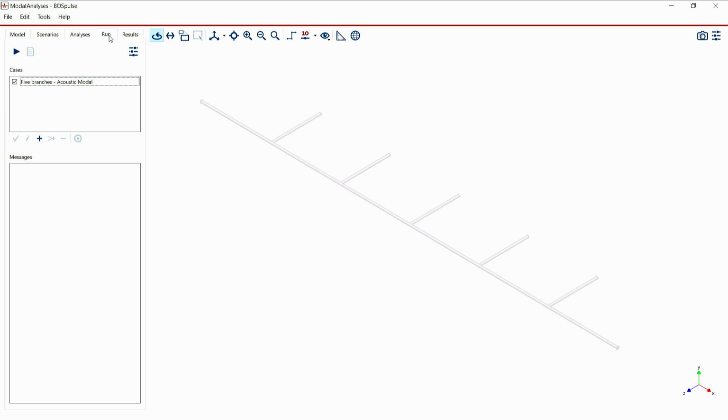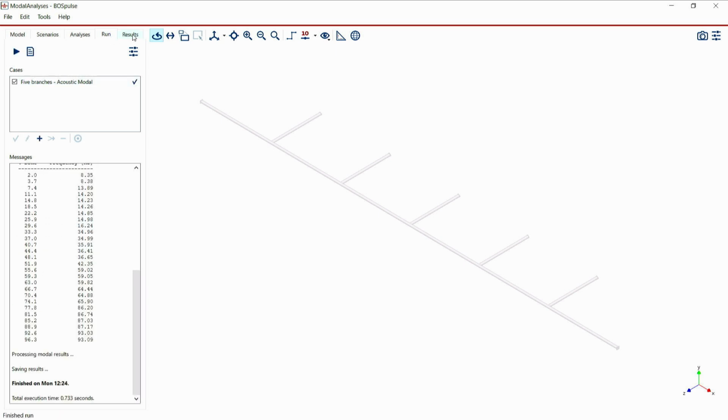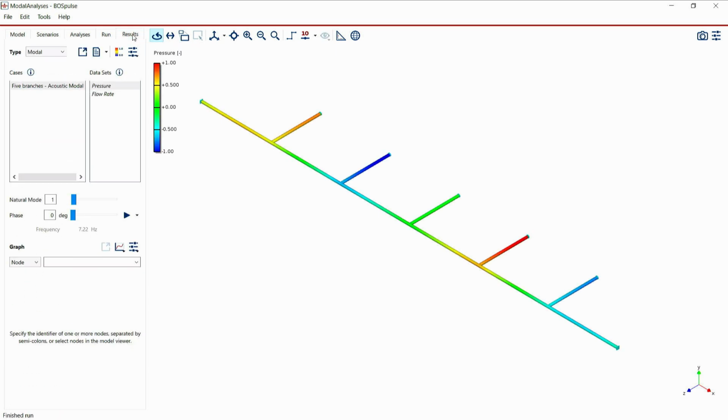Running such a simulation allows you to quickly identify any modes in your system. So this will allow you to quickly see whether there are any possible resonance frequencies which can be excited if you run your pump or a compressor at a certain frequency.